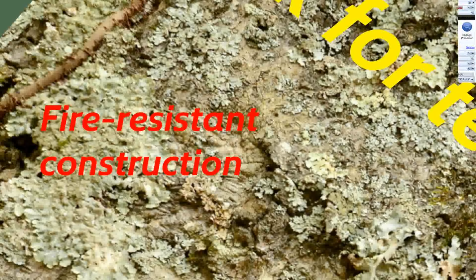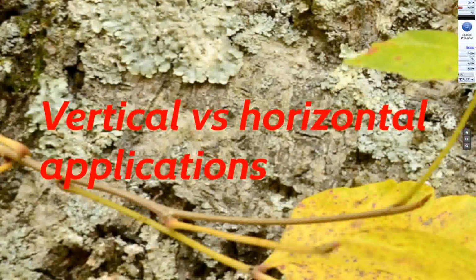Another one, this one relates more to EIFS than anything else. I've looked at lots of EIFS evaluation reports over the years, and none of them allow use of the product on overhead horizontal surfaces. So if you're doing a canopy, you need to go to DEFS or some other product. You're really not supposed to use EIFS in that manner.